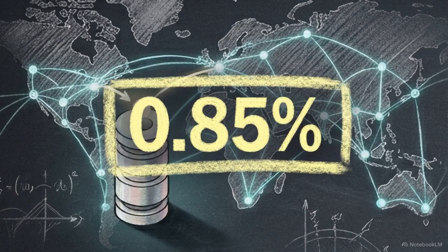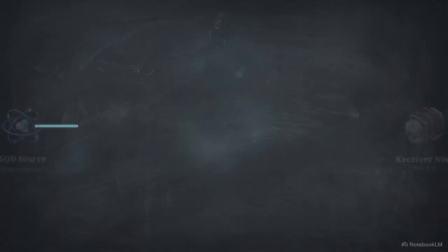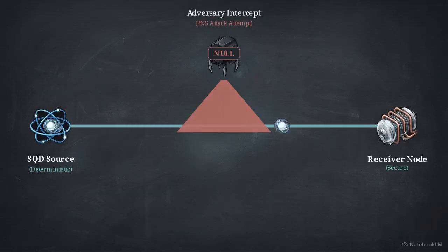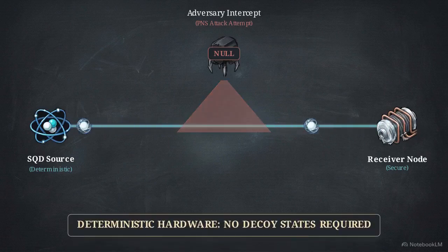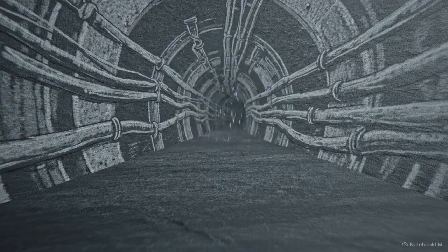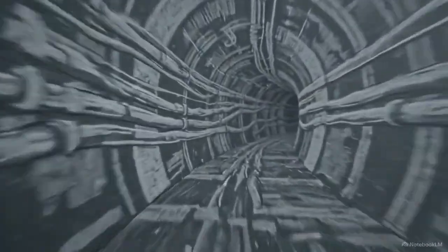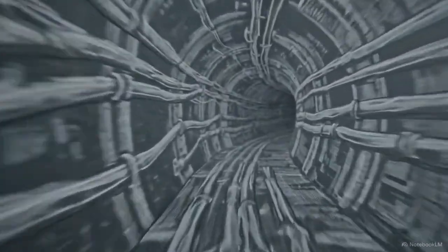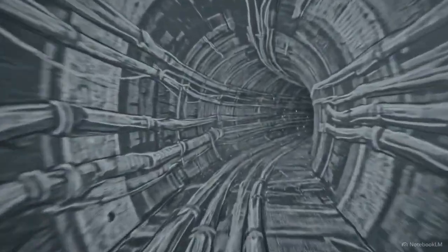Recent studies by Jipeng Wang, Umair Abbas, and their teams measured the residual multi-photon probability for this setup at just 0.85%. This deterministic profile neutralizes the photon number splitting attack at the hardware level, removing the need for legacy decoy state monitoring. Single photon generation is only the first step. That state must then survive transmission through the vibrations and temperature swings of underground urban fiber.